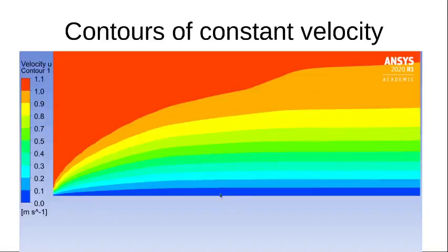But at least you can see the thickness of the boundary layers. I have made the scale in the y direction 20 times the scale in the x direction. So if this looks like 5 centimeters while this is 30 centimeters, this is actually 5 divided by 20, which is 2.5 centimeters. Right, so that is the thickness of the boundary layer that I have. The thickness of the boundary layer goes close to about 2 centimeters here, and the velocity reaches close to 1 at that location. Okay.